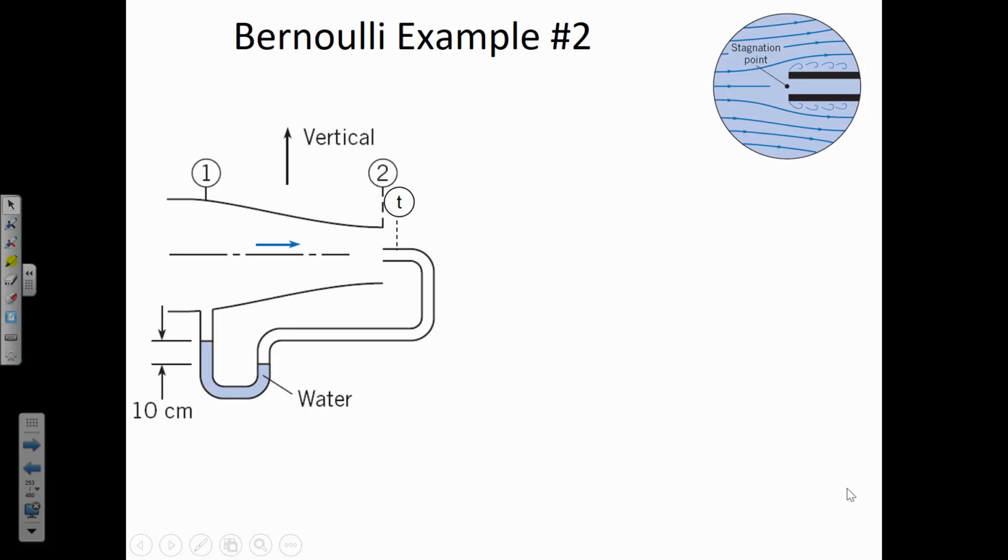So in other words, the energy along the center line, we're going to assume that the energy is constant. Remember, we've got this magical inviscid fluid where there's never any energy losses because it's inviscid, meaning it has no viscosity. That means that it never loses energy due to pipe friction. Now, of course, there's no magical fluid that's completely inviscid, but as long as we apply Bernoulli's equation between 2 points that aren't too far apart, then there's going to be so little energy loss that we don't have to sweat it.